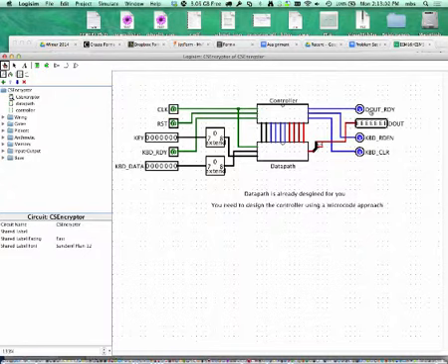You'll have to submit the contents of the ROM as well as, of course, the schematic, and test it out on a variety of cases. It's a very simple encryptor, so type some text and see whether it comes out right. Check it for different values of keys, and also check it for different clock speeds. Very slow clock speed as well as very fast clock speed. So that's what's happening.